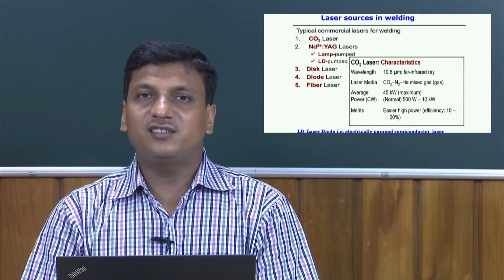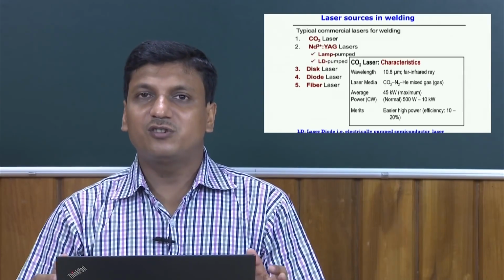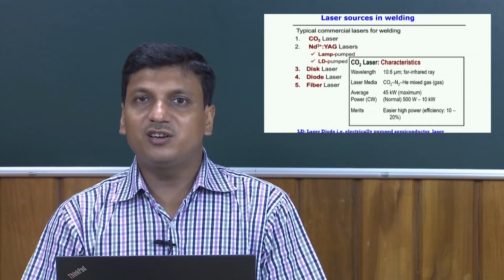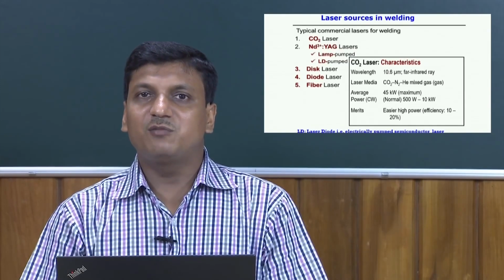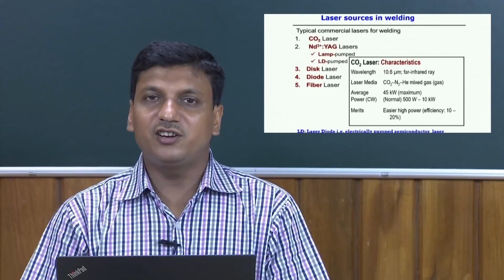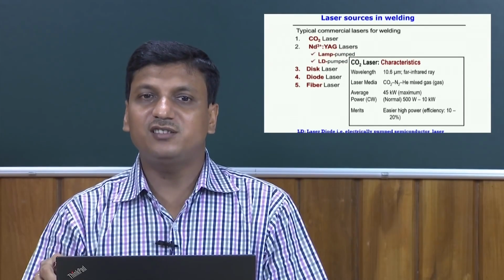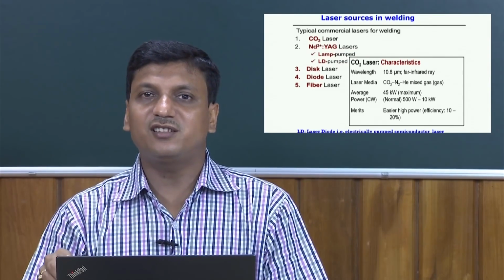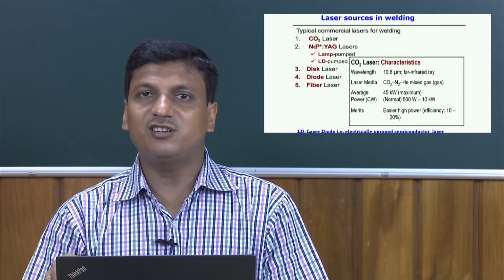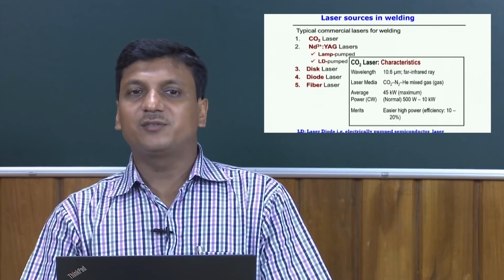The Nd:YAG laser can be useful when more precision is required in the welding process, or for very thin sheet. It is possible to use the Nd:YAG laser in general because its wavelength is 10 times less than the carbon dioxide laser, and it is also possible to focus the Nd:YAG laser into a very small zone as compared to the CO2 laser.